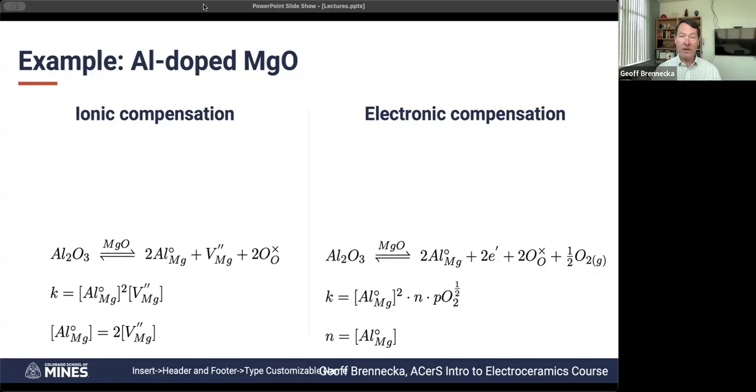But you're right. If you sort of flip things around, and you're sitting at a boundary where I mentioned before this potential solubility limit, maybe it's more soluble at high temperatures, and then you can quench and keep things in that high temperature state, or you can slowly cool down and precipitate out a second phase, and you can accelerate that or slow it down by changing PO2 if this is the scenario.